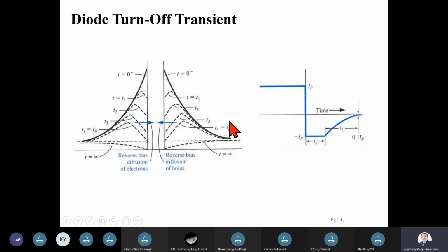It is just assumed to be constant, and it can be argued to be approximately constant by virtue of the very similar slope in the minority carrier profiles here, before the concentration reaches equilibrium. Once it drops below that, the current will start to decay significantly towards the reverse saturation current value.